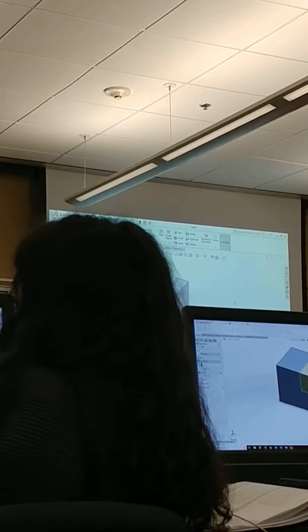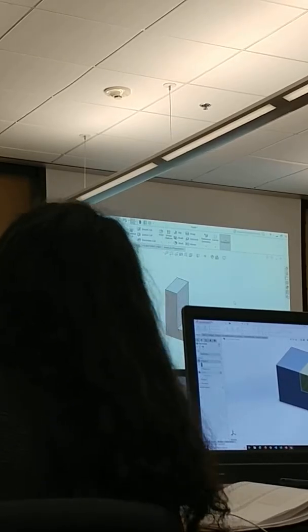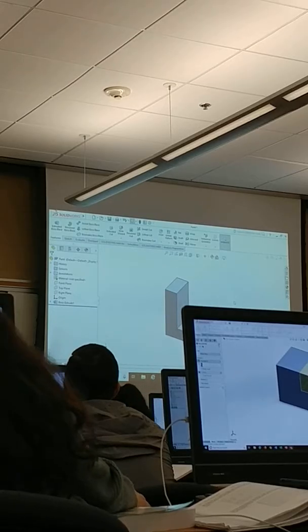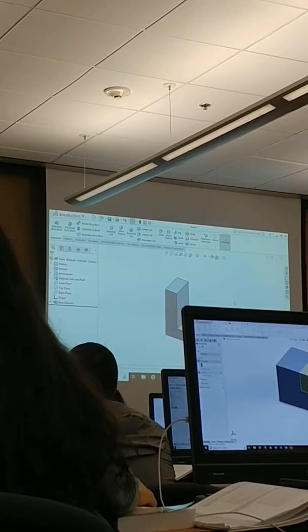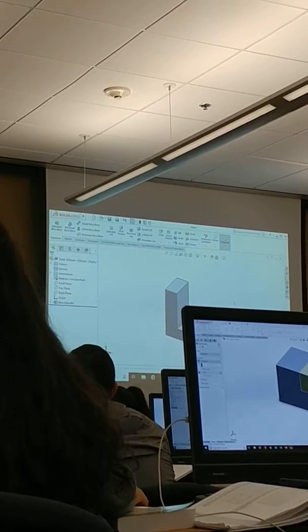And then you can work with the machine shop, figure out what you need to do to modify it a little bit if needed. You put a bigger radius in there because the cutter has a big radius, whatever the case is, and do it that way. But if you start off forcing it to be done one way, then that's the only way that it'll ever be made.